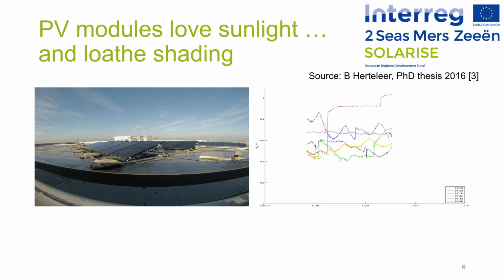As you can see in this video and the animation to the right, PV modules can see significant power loss and efficiency loss due to shading. And as you can see in the still version now, you have up to 60% power loss of a PV module as a result of the shading of those thin poles falling on the modules.